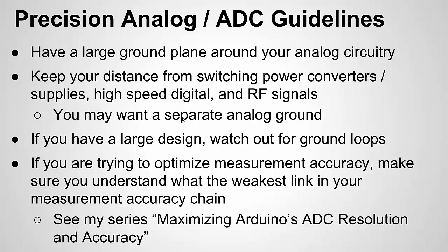As a summary, like I mentioned, ground is not ideal. So let's say you have a design that has 2 separate PCB boards in it, and each of those PCB boards shares a common ground. Well, let's say you use 2 wires to connect the 2 PCB grounds together. Well, if those wires are in different spots on the board, what can actually happen is you create basically current flow between the grounds. So, like I said, ground is not perfect. So often, if you have 2 separate PCBs, one ground might be at a slightly higher or lower voltage level than the other. And the 2 wires that you have connected them can actually lead to a current flow, and that can cause a lot of problems or inaccuracies with your analog circuitry.